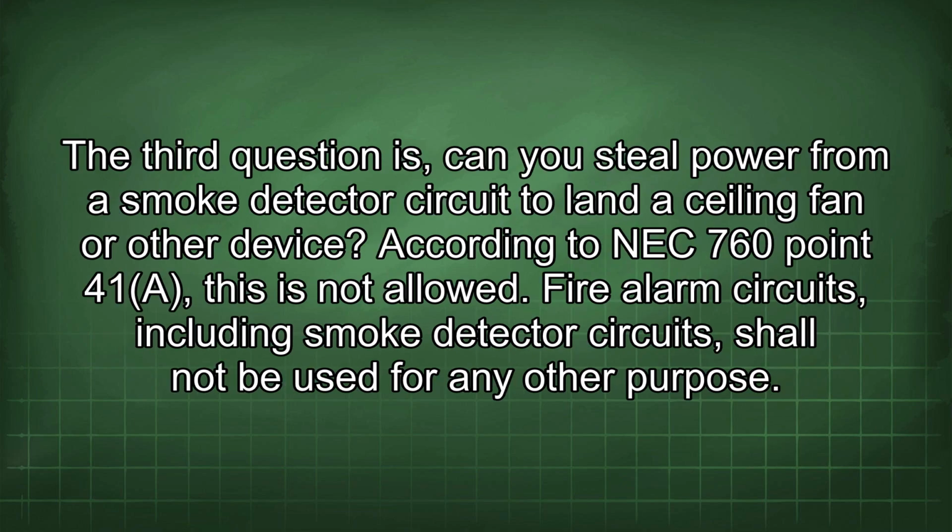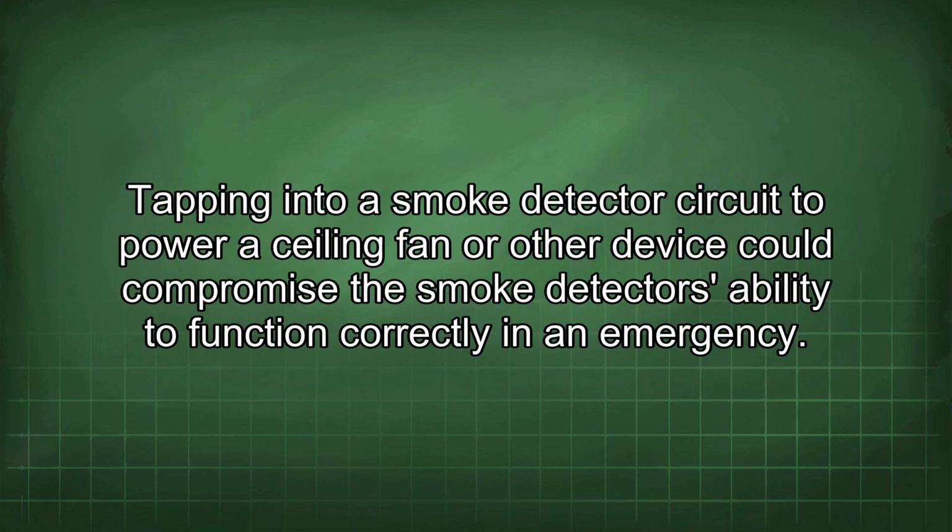The third question is, can you steal power from a smoke detector circuit to land a ceiling fan or other device? According to NEC 760.41a, this is not allowed. Fire alarm circuits, including smoke detector circuits, shall not be used for any other purpose. Tapping into a smoke detector circuit to power a ceiling fan or other device could compromise the smoke detector's ability to function correctly in an emergency.